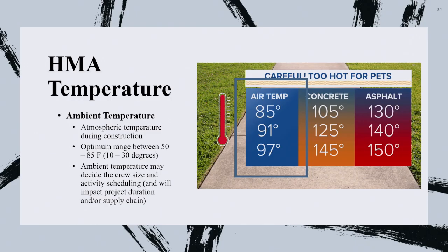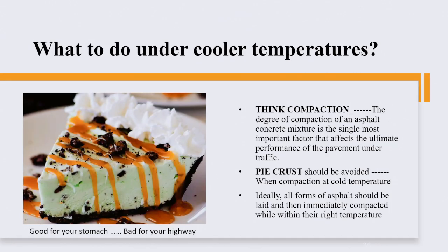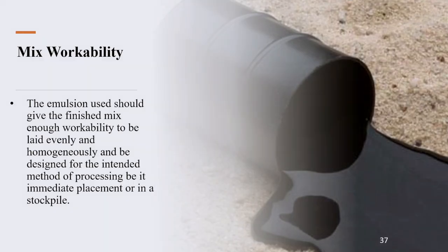So this is a very important parameter when it comes to working with asphalt, because again, you don't want to end up with that pie crust thing. You don't want to end up with very low durability, predominantly raveling, that could exist if you end up with the pie crust type of asphalt mix, or asphalt compacted mix.